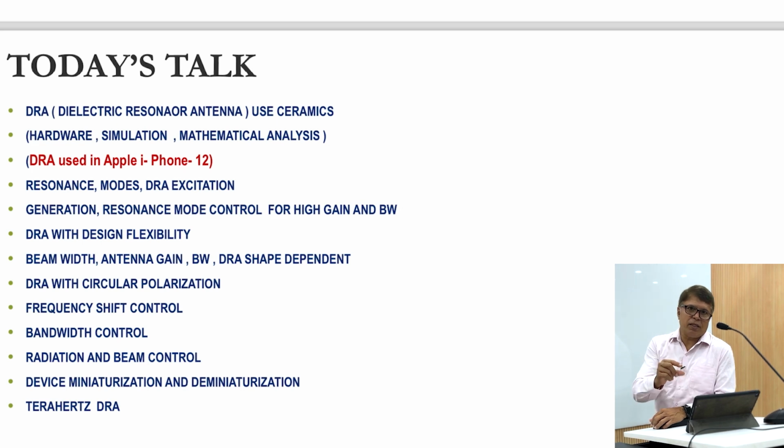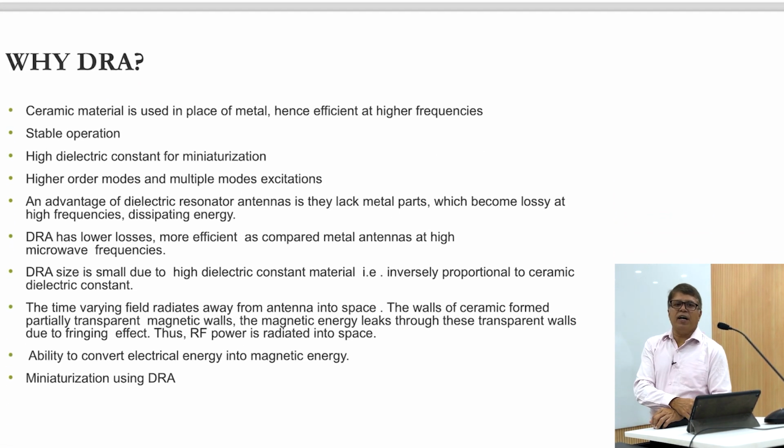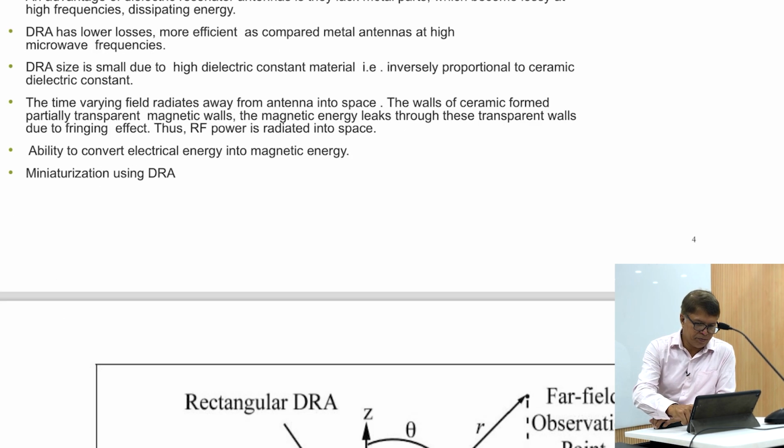Now coming back to today's topic, why DRA? This is a crucial question. We have ceramic material, we have stable operation, we have high dielectric constant, we have high efficiency, we have lower losses, and we have size miniaturization techniques. The basic phenomenon of DRA is that the ceramic or dielectric material will resonate at a particular frequency, and the resonant frequency will depend on the dimensions, input excitation, and other coupling techniques on which these modes of operation will depend.